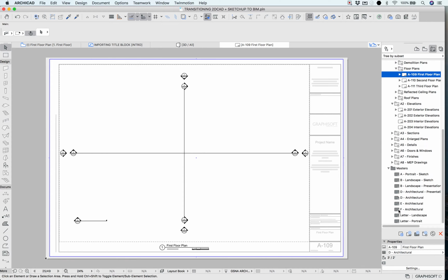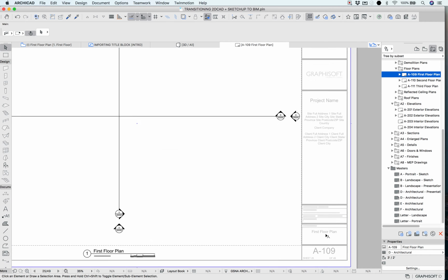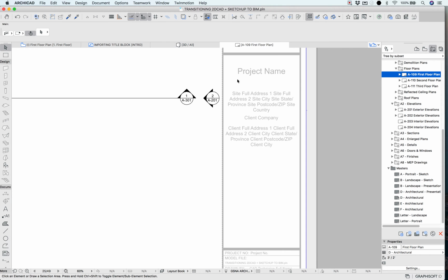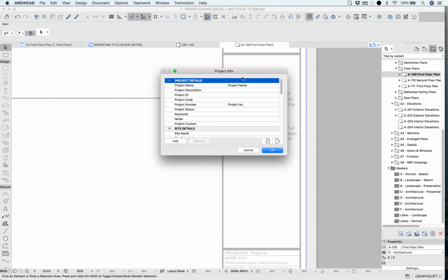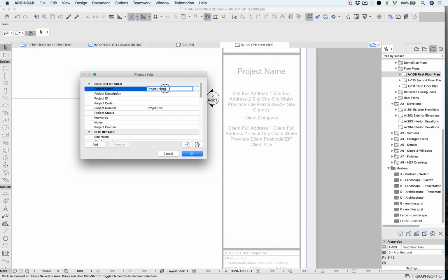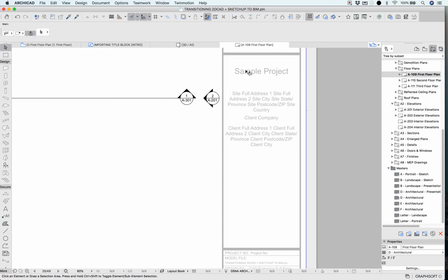So these masters can be customized. It's really not a big deal. If you want to create your own custom title blocks, you can edit some of the information that's here. One large part of how we are more successful and efficient with changes is through this auto text. So things like project name and standard information that needs to carry through our set, I can enter it in one place, right? I'm going to enter it here, and then that's going to update anywhere that I'm requesting that information.